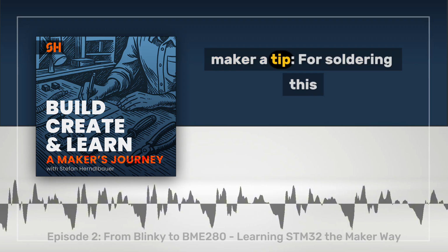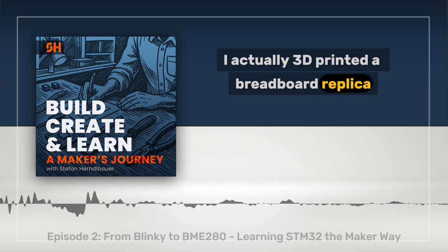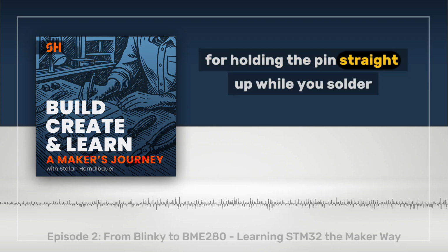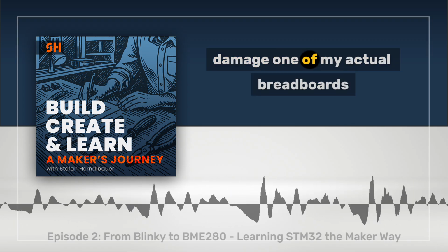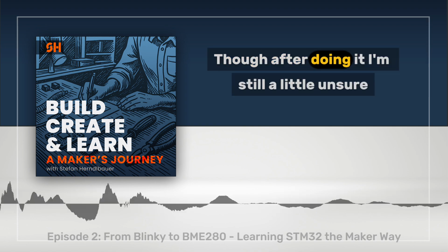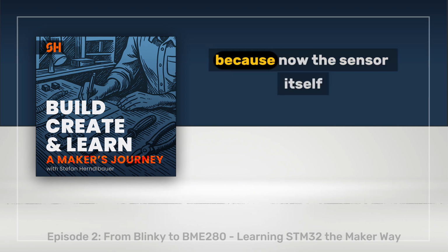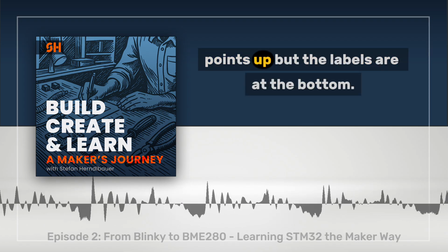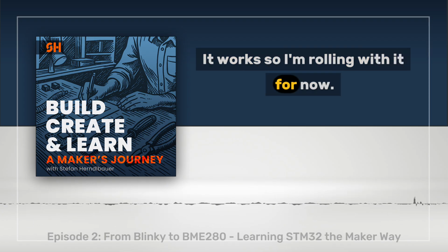Oh, a little maker tip for soldering this. I actually 3D printed a breadboard replica. It's perfect for holding the pins straight up while you solder, and it meant I wouldn't accidentally damage one of my actual breadboards with heat or stray solder. Though after doing it, I'm still a little unsure if I put it in the right direction, because now the sensor itself points up, but the labels are at the bottom. It works, so I'm rolling with it for now.